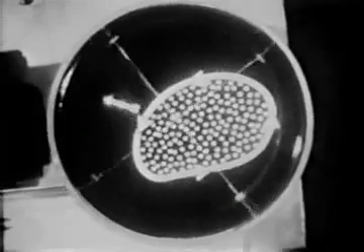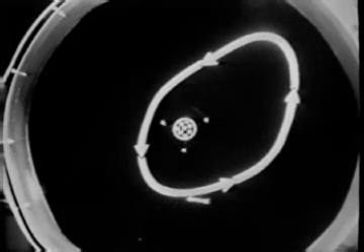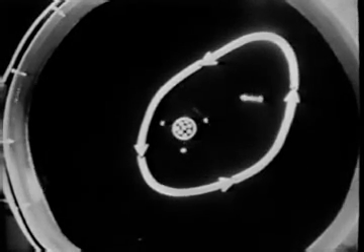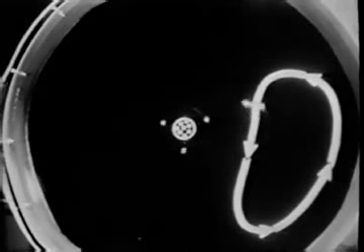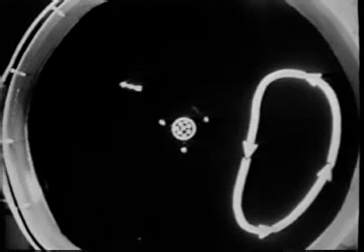In the spiral vortex tank, the flow is non-vortical, except for the concentrated vortex core, which accounts, so to speak, for the whole motion. All fluid circuits surrounding the core have the same circulation, because they contain the entire vorticity flux. All fluid circuits not surrounding the core have zero circulation, because they contain no vorticity flux.